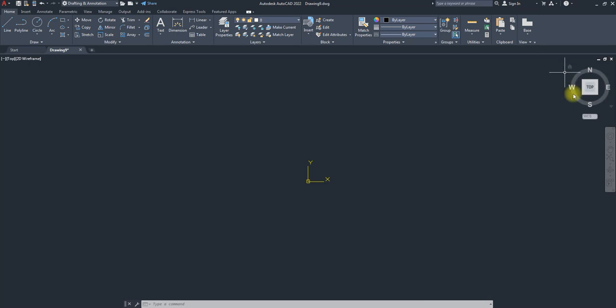And you can notice under this view cube, what do you have? You see WCS. Because when we open this drawing, AutoCAD gives us an origin. So if we decide to shift this origin, we select this guy. If I move this origin away from here to somewhere else, let me just click on it, and let's say I want to move it here. Notice what it says now, because we have moved it away from where it normally is. Then you notice we have our new user coordinate system, so we can take it back to the World Coordinate System, and it shifts back.